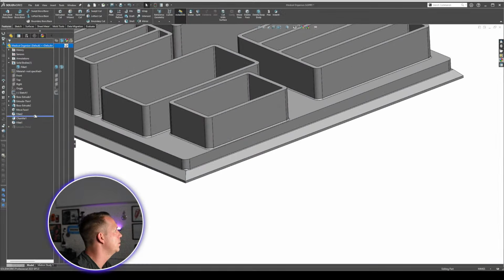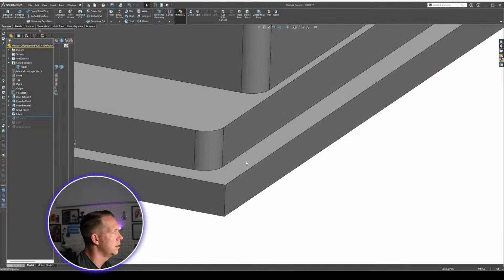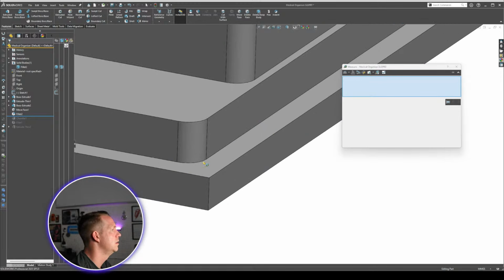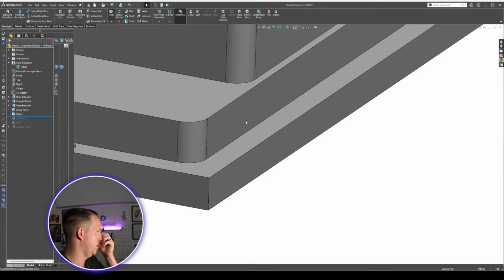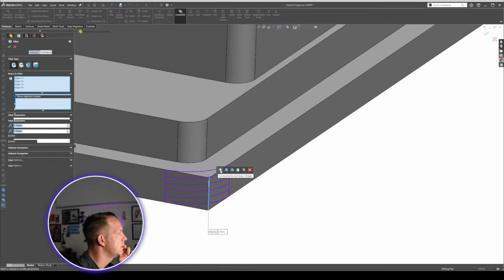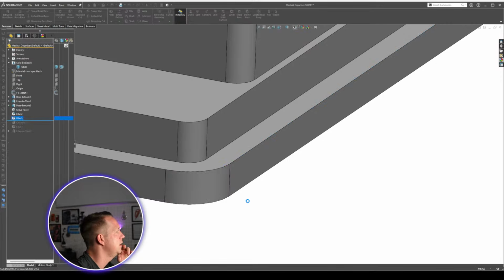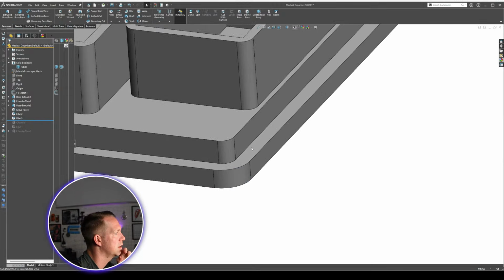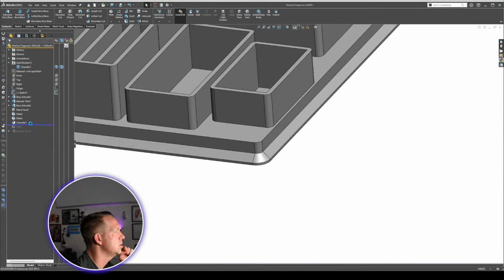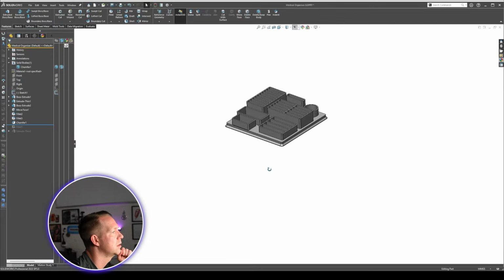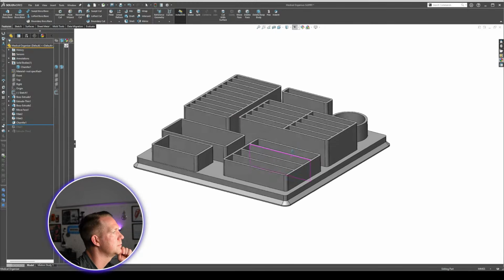From a design point of view, how you want to do that, let me roll back up in the tree. This distance here is 3 millimeters. So whatever this is, I want to add that onto whatever the fillet's going to be on the outside, which is 5.5. And what that'll give me is consistency in this curve. Like, this is pretty basic geometry. Now when I do the chamfer, see, the chamfer works and is consistent around those edges. Okay.